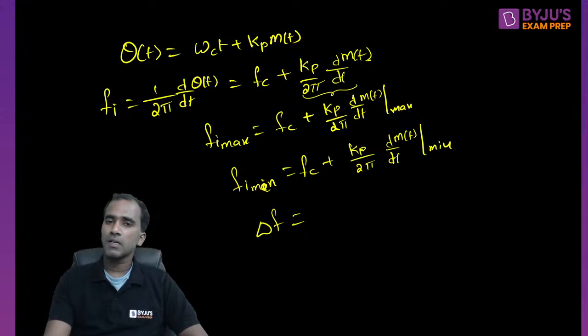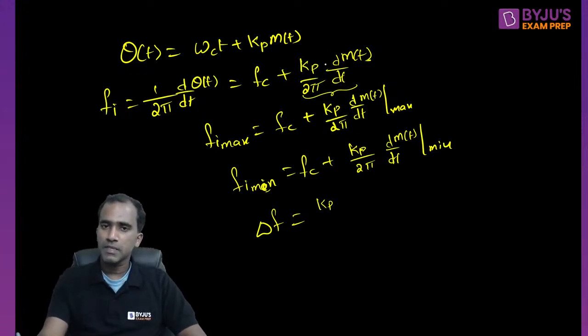This is the phase part, and this is the part responsible for phase deviation. And whatever is the maximum magnitude of this part, that we can call the maximum phase deviation. The term that is responsible for frequency deviation, in that term, find the maximum magnitude.